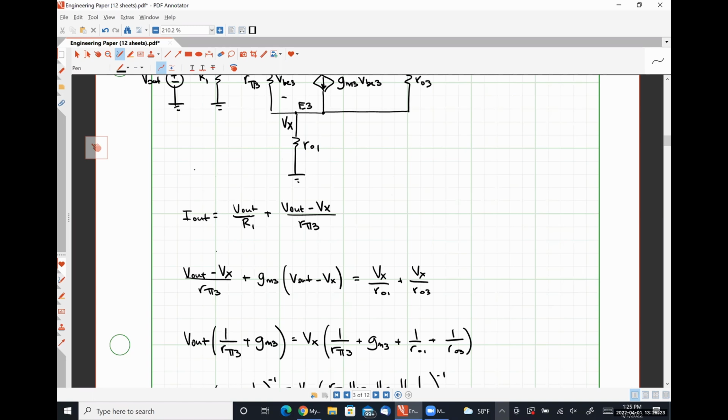What is the VIDM stuff? What do you mean the VIDM stuff? That's very vague. There's a lot of deriving with the voltage IDM. I'm not expecting that, so once we get to a half circuit, that no longer matters. That was before we had developed the concept of half circuits. Let me say another thing. There's not going to be any DC operating point for differential pairs. So that hyperbolic tangent thing or anything like that is not going to be on the test.